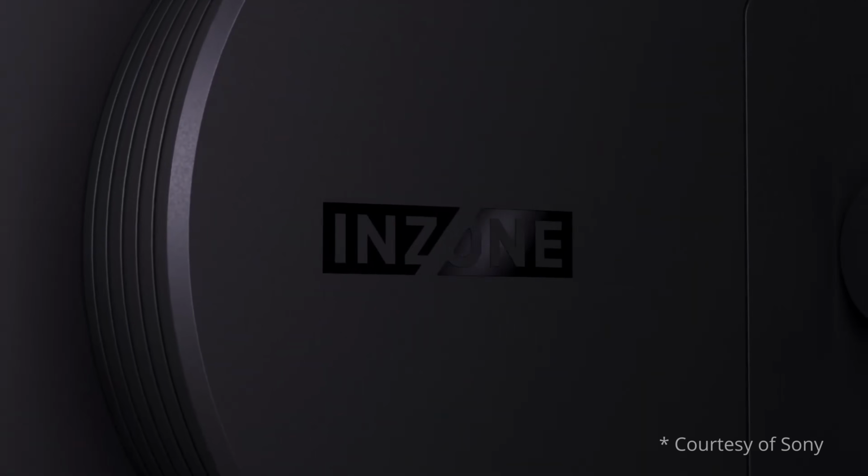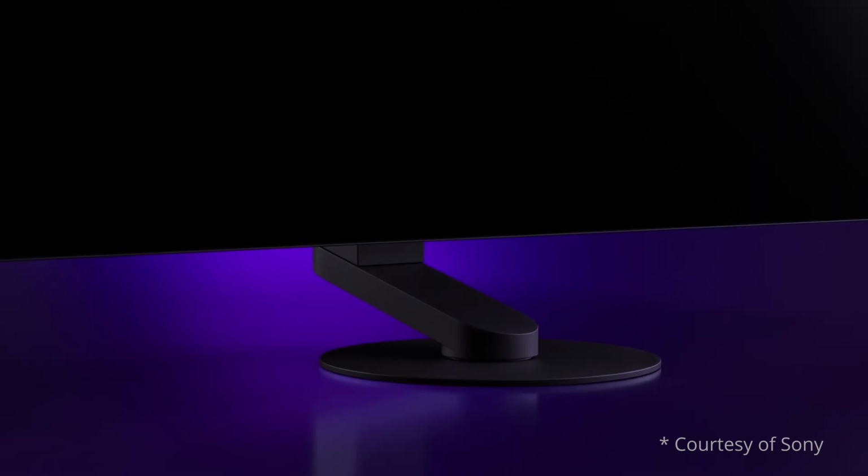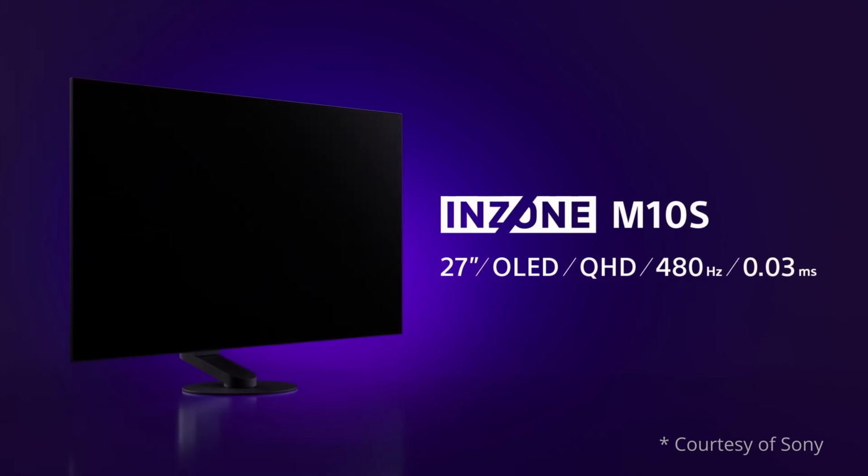Adding DP 2.1 for the sake of it at lower tiers to some of these screens is pointless, we think, beyond marketing promotion, as it doesn't avoid DSC usage anyway, as we've seen from some of the early DP 2.1 marketed monitors already. Lower tier DP 2.1 could, however, be used for some lower spec screens to support uncompressed signals, although it's less likely again for the same reasons we've just discussed.